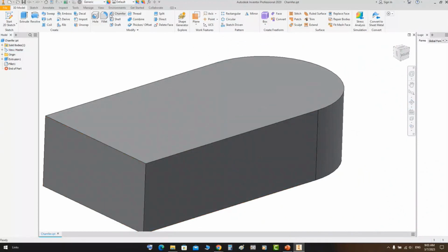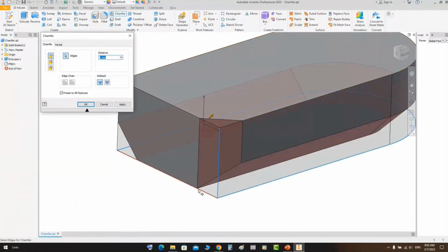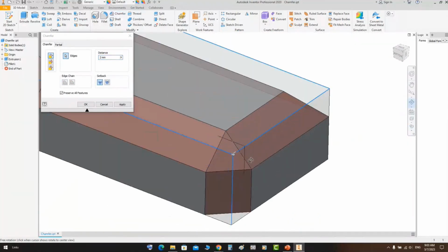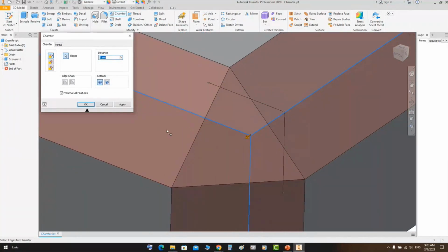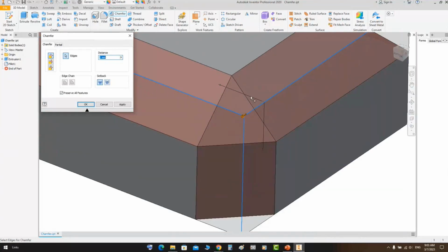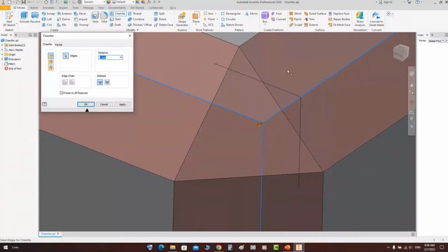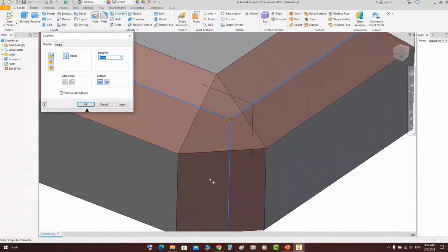Okay, let's discuss another option for the chamfer. If we have 3 edges like those here, we have the end of this chamfer, which is the intersect between the faces. You can change the setback configuration. Here, the result gives you a new surface. So at the intersect between the 3 surfaces, here you have first surface, second surface, and third surface along each edge, you will get another face.